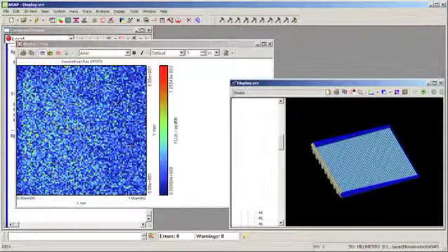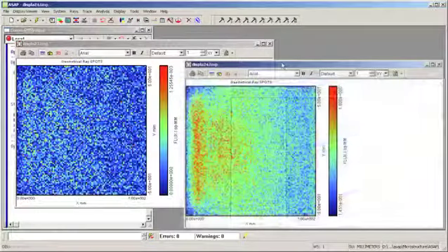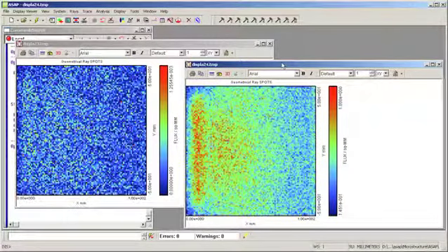If we look closely at this result, as well as the unit cell result, both results show large statistical fluctuations because we have not traced enough rays. Let's look at the results of a longer ray trace that uses 100,000 rays per source so we can get a better picture of what the irradiance looks like. This ray trace has already been performed, and I'm just going to show the result. Here is the result from an explicit ray trace that took 45 minutes.